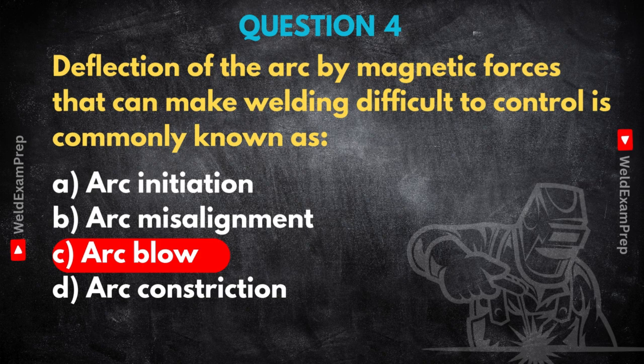Oh, absolutely. Increased spatter is common, but also more serious things like lack of fusion because the heat isn't going where it should. Porosity, inconsistent bead shape. An inspector would look for those signs. So how do welders deal with them? Well, sometimes switching to AC current helps, as the alternating current disrupts those steady magnetic fields. Or they might change the ground clamp position, sometimes using 2 grounds. Maybe change the angle of the electrode, or even use shorter arc lengths. Preheating can sometimes reduce it too.